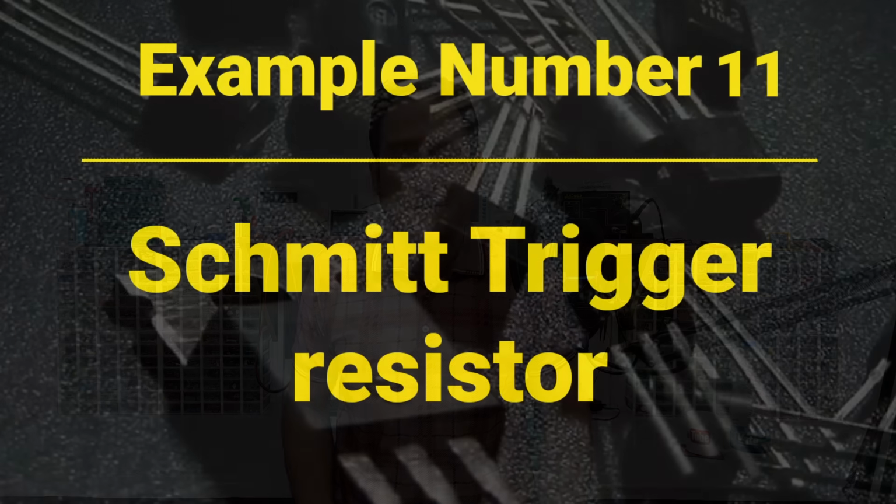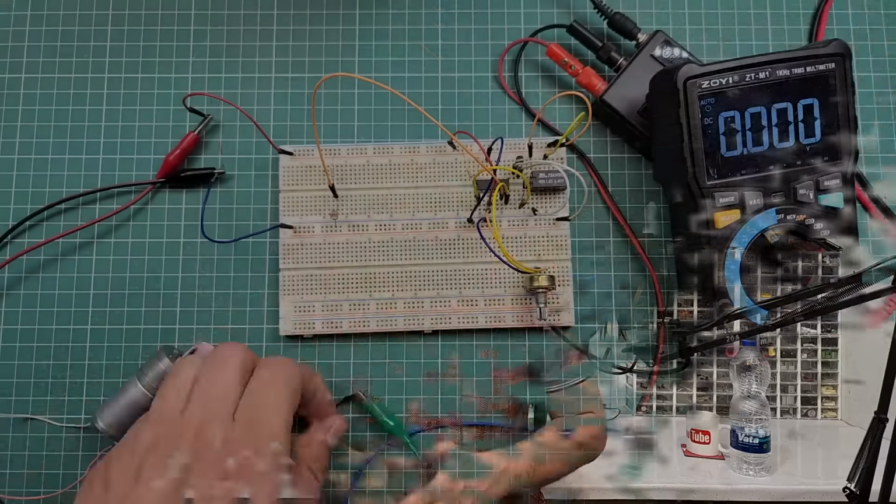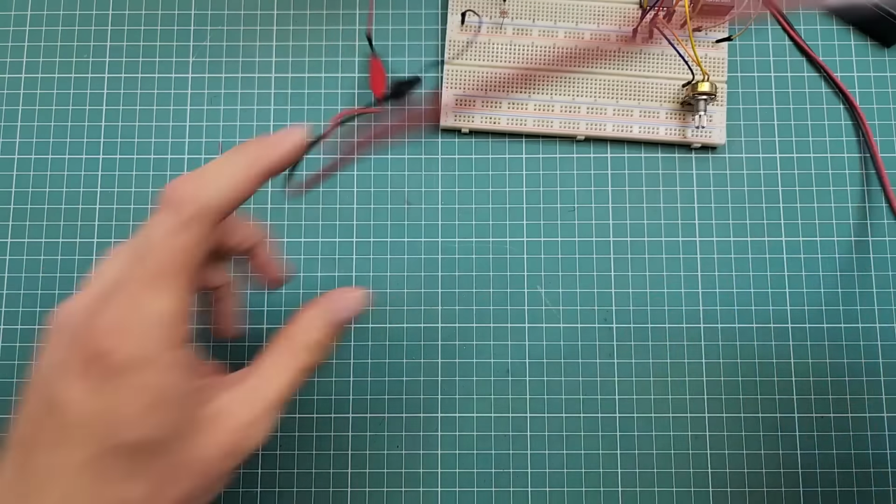But we can solve this problem by using only one resistor. Example number 11, Schmitt trigger resistor. In ordinary comparator systems, there is one threshold voltage, like the reference voltage in the previous example. The sensor voltage is compared to the single reference voltage. But in Schmitt trigger comparators, we have two reference voltages.